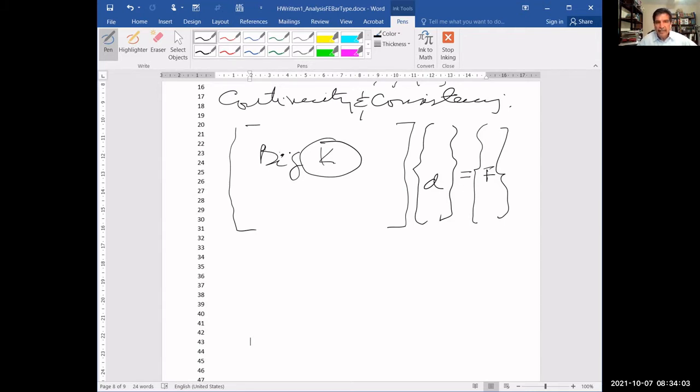So this system here, in that case, would have this matrix, 300,000 columns and 300,000 rows. That's a big cake. Of course, these are the unknowns, and these are knowns. So this is a big problem because you can use, for example, very small elements. And the problem is that in that case, the size of these arrays is going to be very large, and of course, that takes more time to solve them. So we have to be very, very clever in discretizing the structure.